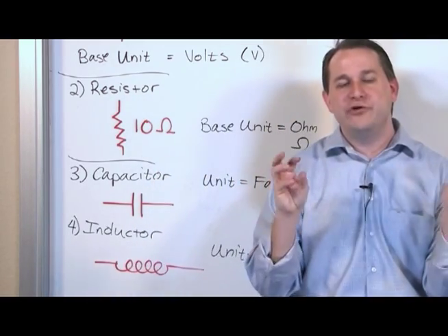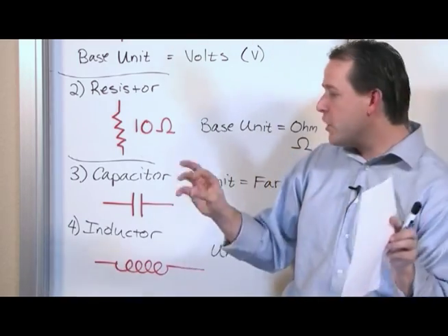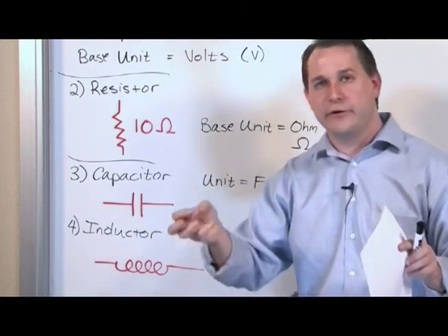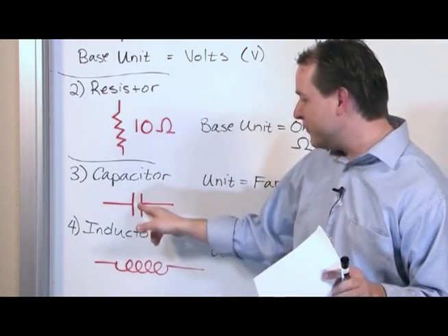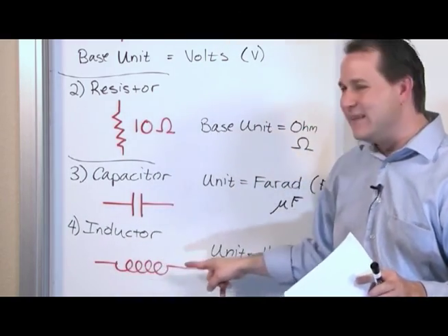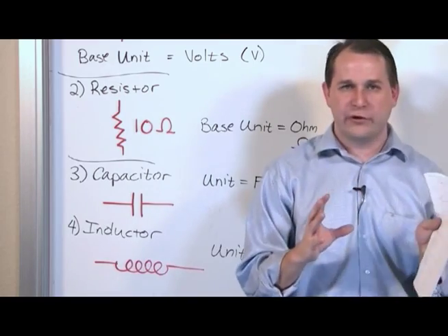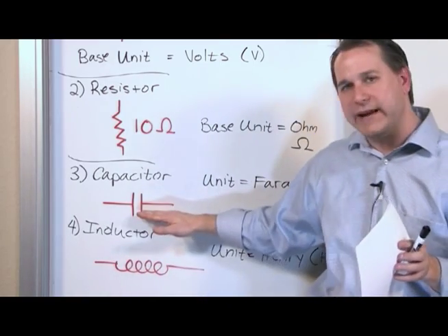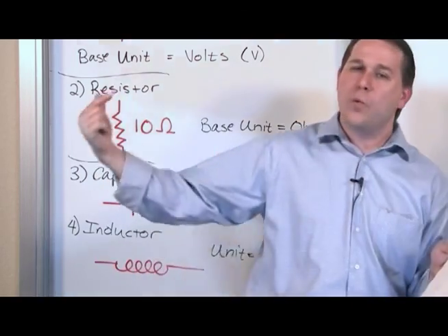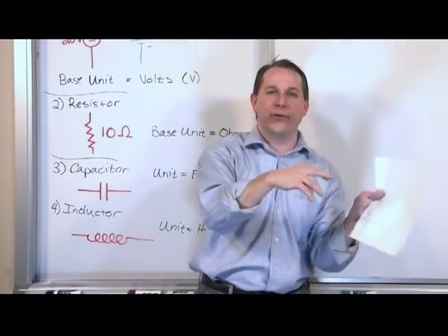And you have chosen those values such that when you turn the knob, by the way, when you turn the knob, usually you're changing the value of the capacitor in the circuit. When you turn the knob on the radio, you're changing the value of this capacitance. When you do that, these two guys are in the circuit together, and it's kind of hard to explain without showing a real circuit, but basically, since this guy stores energy in an electric field, and this guy stores energy as a magnetic field, when the wave comes in, you get this situation where they start sending energy back and forth to one another.